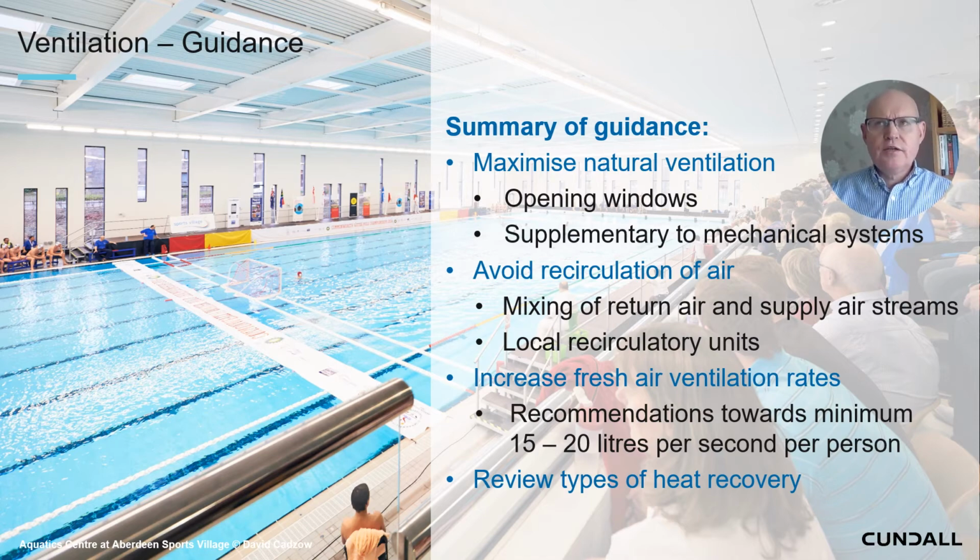Current standards for the likes of schools, office buildings, etc., generate a figure of between 8 to 12 litres per second per person, depending on the standards that they're applying. Talk is of increasing that to the region of 15 to 20 litres per second per person, and also reviewing types of heat recovery system.